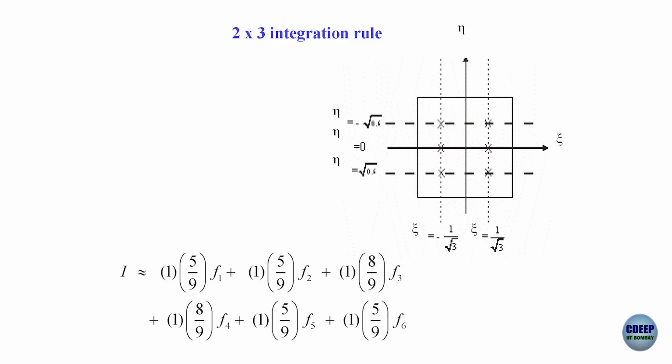So, we have now eliminated, or simplified, this 2-dimensional integration, the double integral evaluation over the domain of the parent element, -1 to 1, -1 to 1, by just simple function evaluations at selected points. The selected points are Gauss quadrature points and the weights are Gauss quadrature weights.